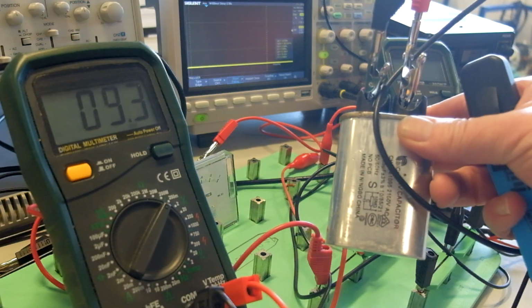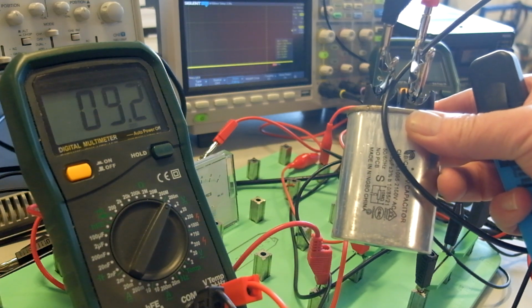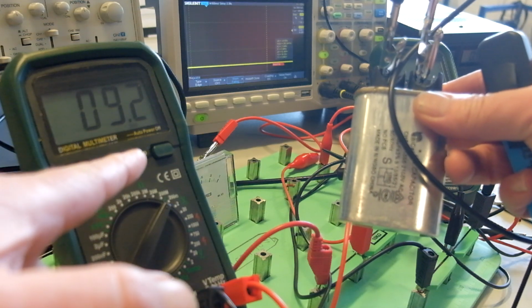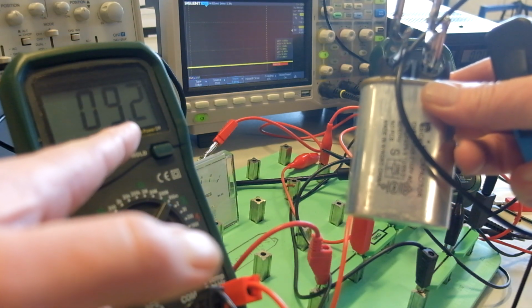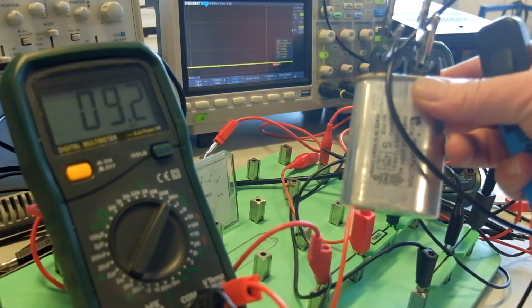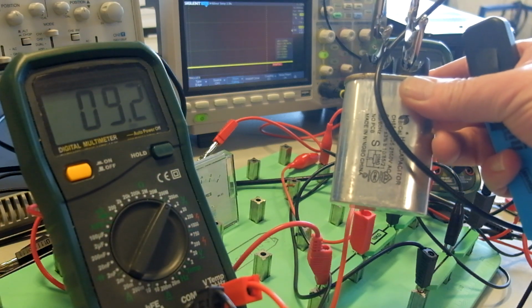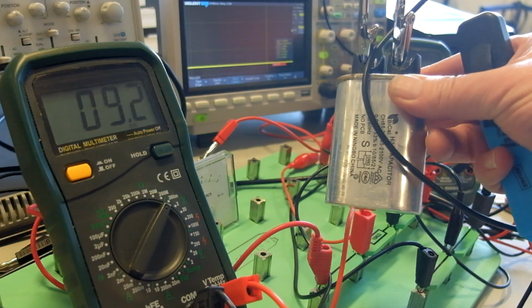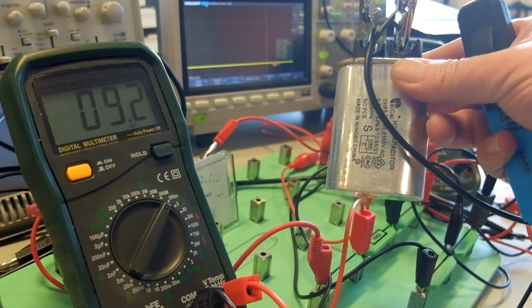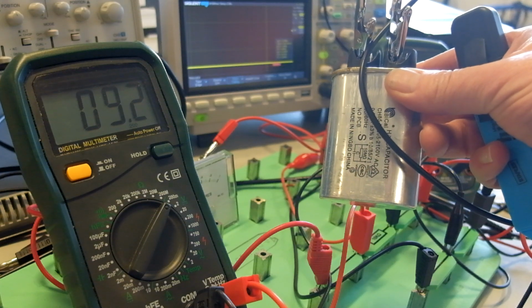So this has a physical 10 megohm resistor connected across it, and we can see that the current hasn't changed much from our reference 10 megohm resistor, showing it's approximately 1 microamp, and it does appear to be in the region of 10 megohms as a reference. So that is the high voltage capacitor.